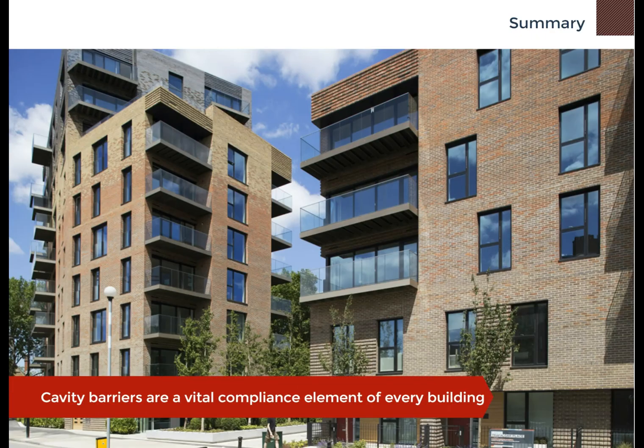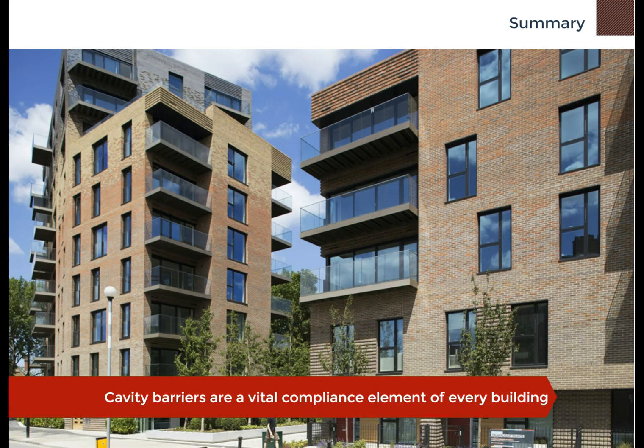Cavity barriers are a vital compliance element of every building. They are particularly important for volumetric modular construction, as there is a gap almost all the way around the modules, except for open-sided modules.